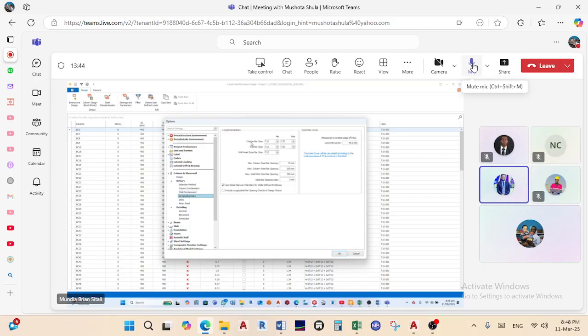When it comes to column bar size, I was just choosing the bars that I want to work with. I said I want to work with anything from Y12 to 32. I could have clicked 10, but I don't want to see 10 in my column. Even 12, I would say okay, it's just because I put it there, but ideally for a high-rise structure like this one, I would just say I want anything between 20 and 32. And when I say okay, it will modify itself to these parameters that I've placed in here. I hope I've answered your question.